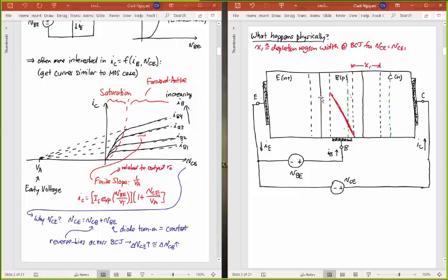So that's going to be my minority carrier injection there. And we know that the current, so I could say J_N, which will be the drift current, is going to be proportional to the slope of this curve. Right, so I can write down number 1 here.